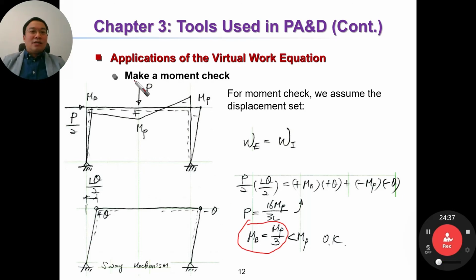That is another application of the virtual work equation to make the moment check. So from now on, you can use this application of virtual work to do the moment check with an independent displacement set.